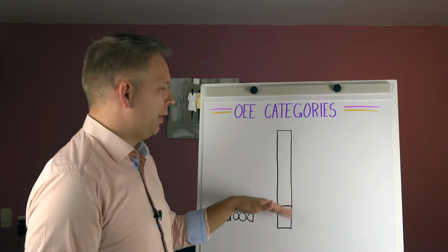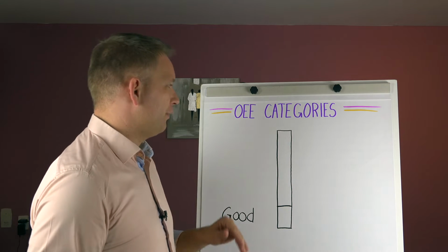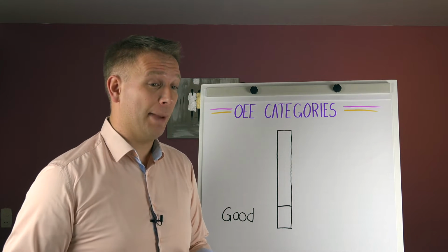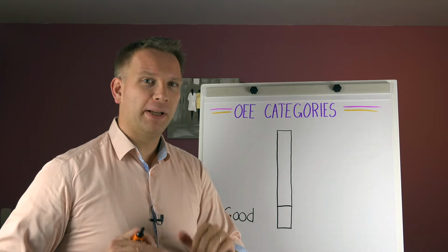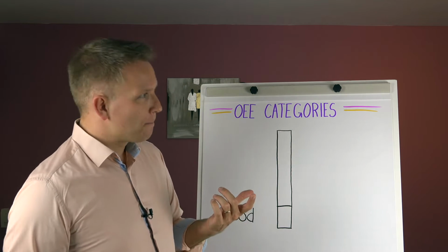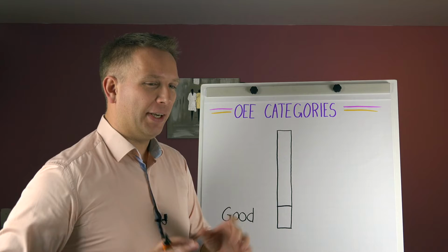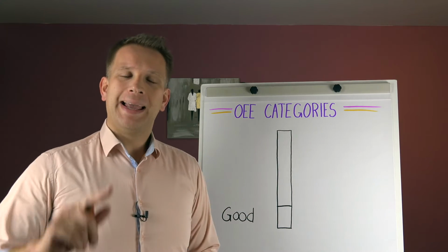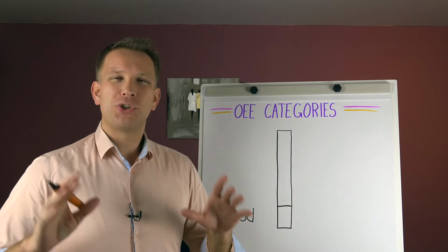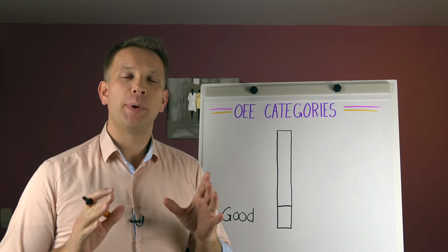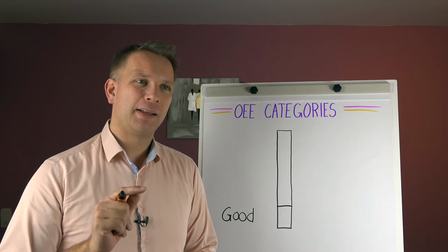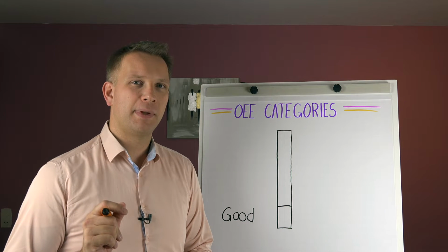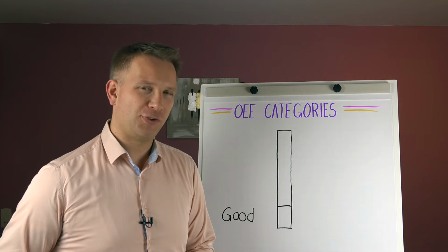Hopefully your OEE is somewhere between 50 and 85 or so. If it's under 50, it's possible, and definitely in practice this happens, but you've got a really low performing line. If it's over 85, I think you're leaving out categories, but that's it. And this is waste, so good and waste. This split, so just knowing the OEE, I think might be a more effective use of your resources and time than the most popular way to measure OEE.